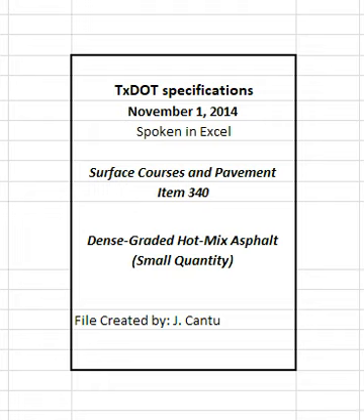The substitute binder meets the specification requirements for the substitute binder grade in accordance with Section 300.2.10, Performance-Graded Binders, and the mixture has less than 10.0 mm of rutting on the Hamburg wheel test, Tex-242-F, after the number of passes required for the originally specified binder. Use of substitute PG binders may only be allowed at the discretion of the engineer if the Hamburg wheel test results are between 10.0 mm and 12.5 mm.